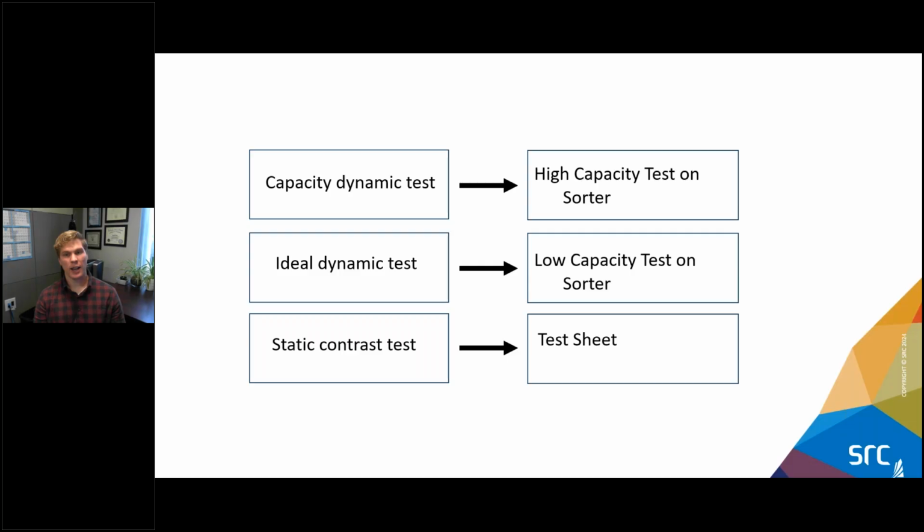And then we could go to the high capacity sorter test. That's after I've picked out the set point I want to go in. And usually if you're dealing with waste removal, the idea is you want to keep all your valuable product and just remove waste. That's usually what it is. So you always try to push it to the nth degree of what you can detect for your valuable mineral relative to the gangue. But once you figure out that point, then you can go to a full capacity test. So this is where you run the machine fully charged. You're going to have those particle-particle interactions. You're going to have those mechanical inefficiencies. And then you can see, based on theoretically what I can achieve, what this machine can actually do.